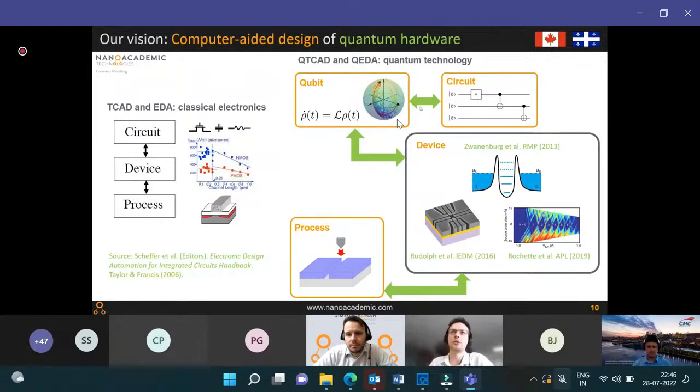And the idea would then be to input that in what we call a qubit simulator, in which the time evolution of a few-qubit system would be calculated using a compact model of the devices, accounting for quantum control pulses applied by the user, and also user-defined noise spectra.